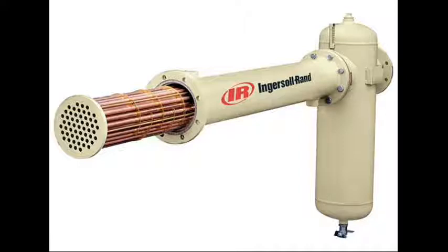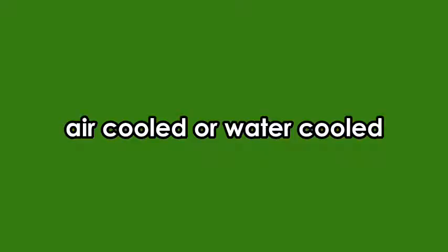In a distribution or process manufacturing system, liquid water causes significant damage to equipment. An aftercooler is necessary to ensure the proper functionality of pneumatic or air handling devices that are a part of process manufacturing systems. Aftercoolers can use either air-cool or water-cool mechanisms.